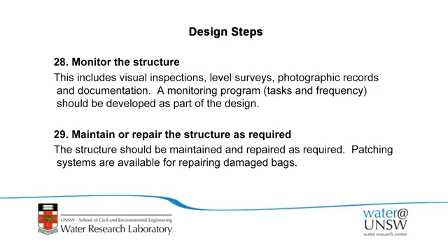So once it is built, monitor the structure, I would always suggest, or develop a monitoring program. It can include visual inspections, surveys of the crest periodically, or documentation. The monitoring program should include what tasks you're going to do to monitor it and how often you should do them, and that's really part of the design.